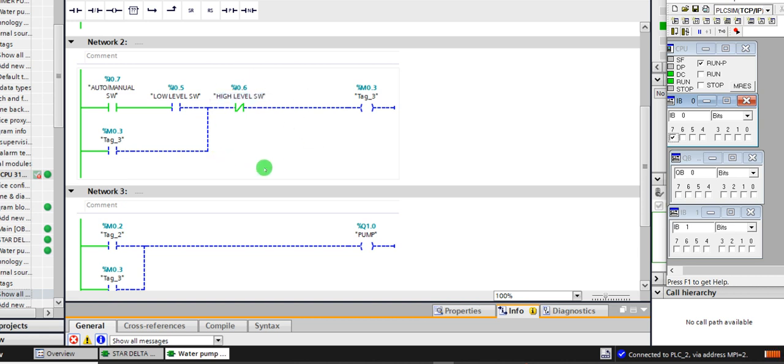So now it is assumed that the tank is full. Okay, now I want to drain the tank so that I will now pump in. So in that case, let me say, okay, the tank is now going to a low level limit. I want to pump now. So in that case, I will activate the low level switch. So go to your activation area and activate 5. Once I do that, look at my pump pumping. It's now pumping.